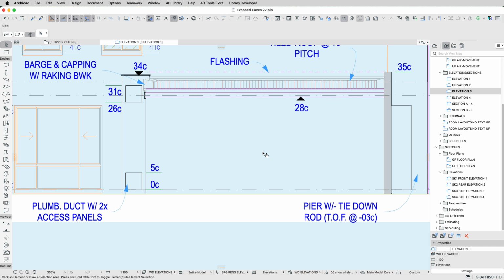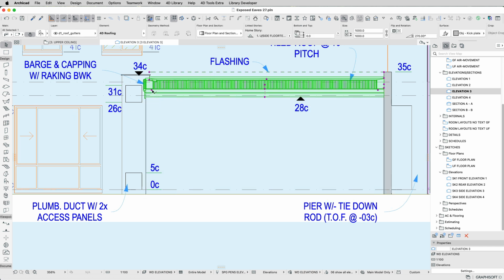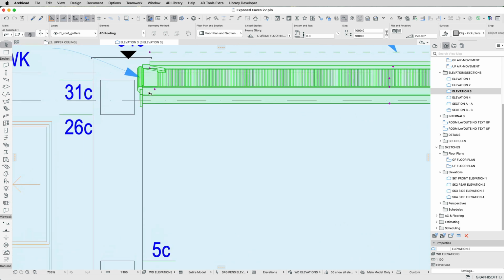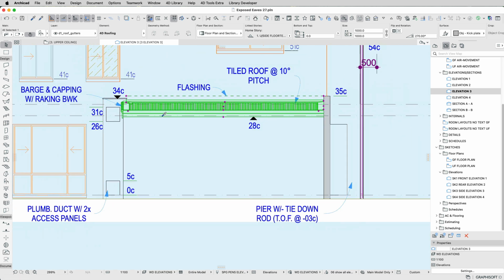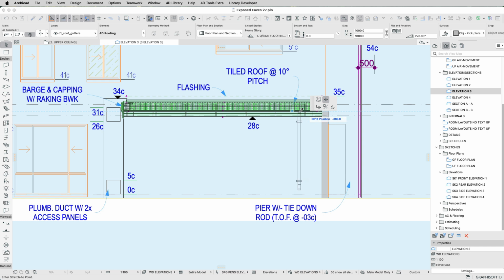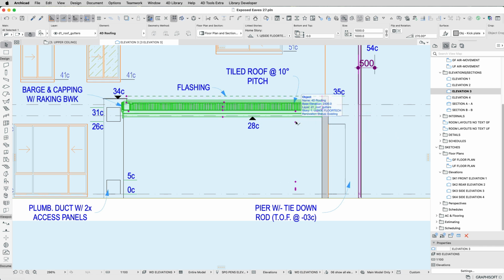Interestingly, through here we've got a zero lot, or a gutter that's closer to the boundary, so it can't have exposed eaves. I'm just going to add a downpipe. So through here I'm adding the downpipe. Let's just place it here, and you can see there that it's set back quite a way from the wall, because that's flush, that eave.